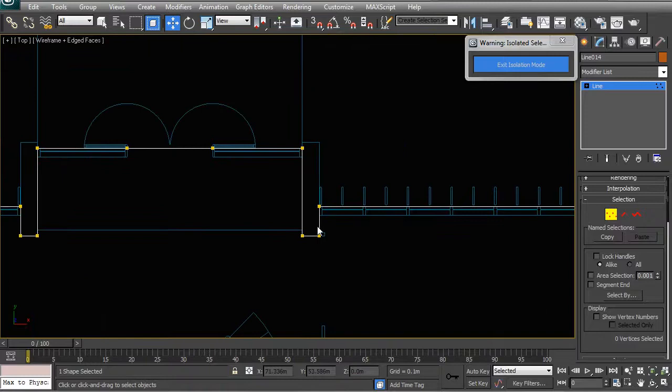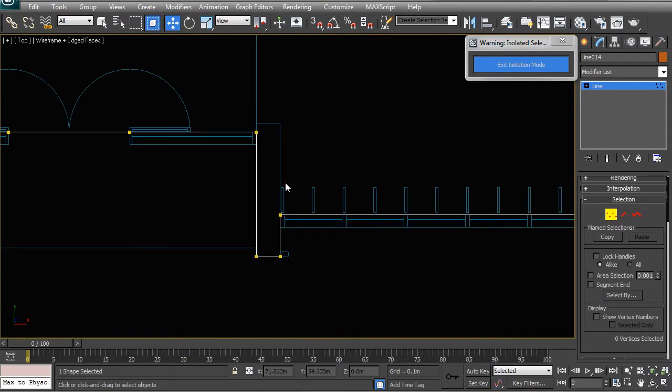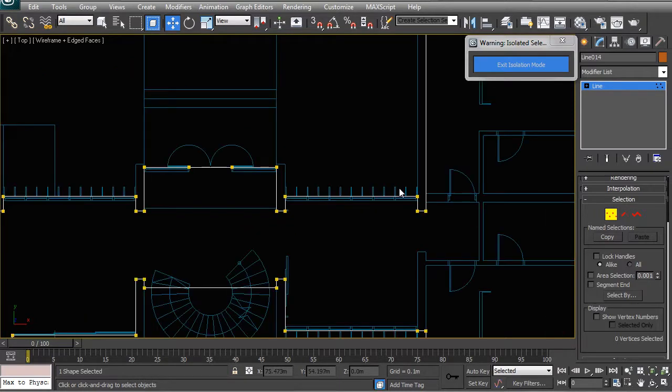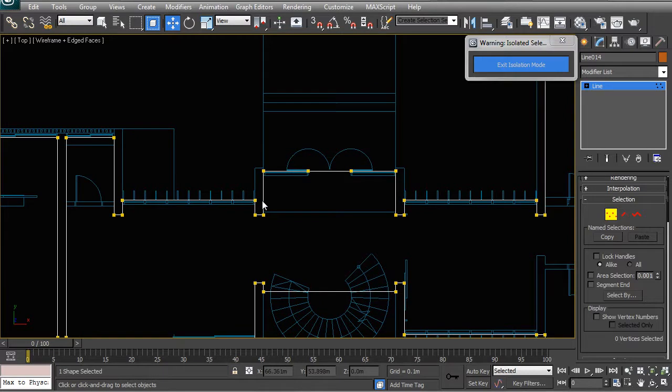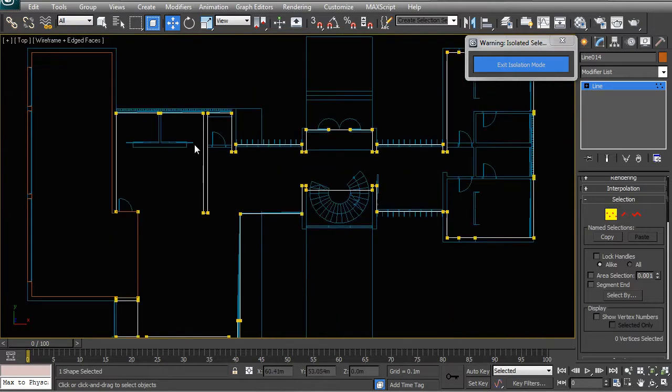Now do note that on the areas where we have the windows standing directly on the floor slab, we do need that floor slab to go all the way out to the outside and not on the inside, because you do see that edge from the outside when you're standing out here. So just keep that in mind as you do all of your edges.